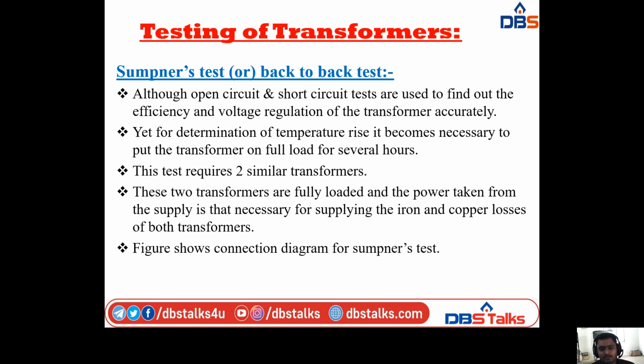Up to now we discussed the open circuit and short circuit tests. Although they are used to find the efficiency and voltage regulation of the transformer accurately, yet for determination of temperature rise, it becomes necessary to put the transformer on full load for several hours.